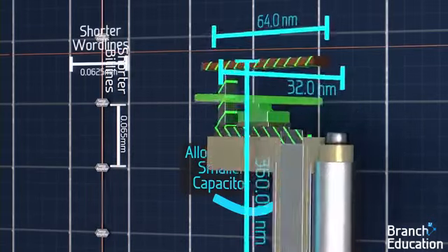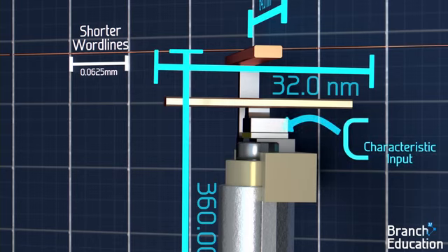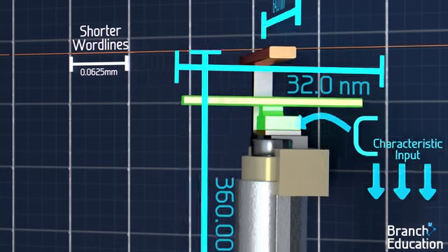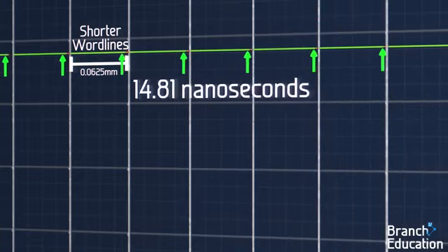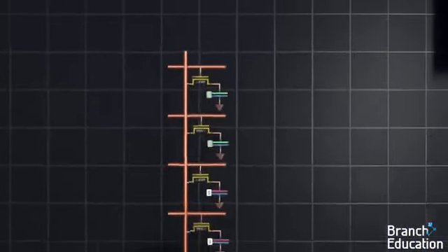By subdividing the word lines, the capacitive load from 8,000-ish transistor gates and channels is decreased, and thus the time it takes to turn on all the access transistors in a row is decreased. The final topic we're going to talk about is the most complicated.